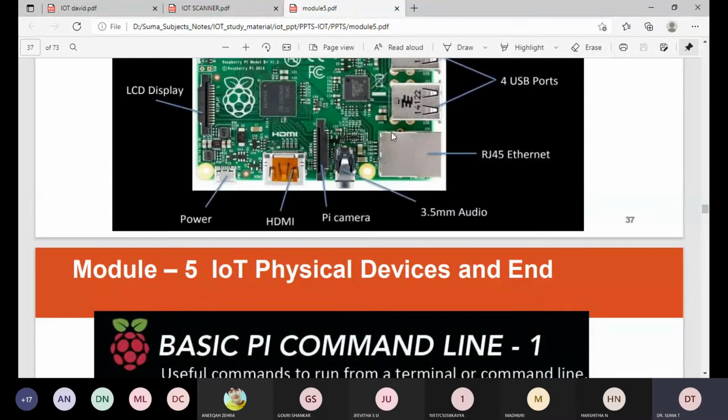It has a VideoCore IV graphics processing unit and RAM. It has a level 1 cache of 16 KB and a level 2 cache of 128 KB. The level 2 cache is used primarily by the graphics processing unit. The SoC is stacked underneath the RAM chip, so only its edge is visible.